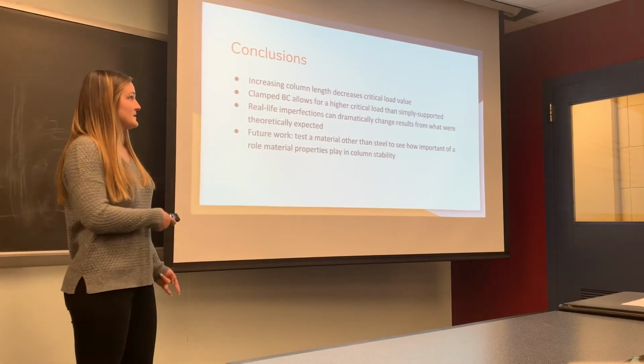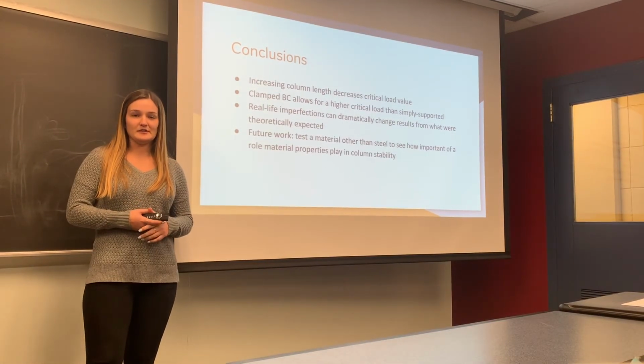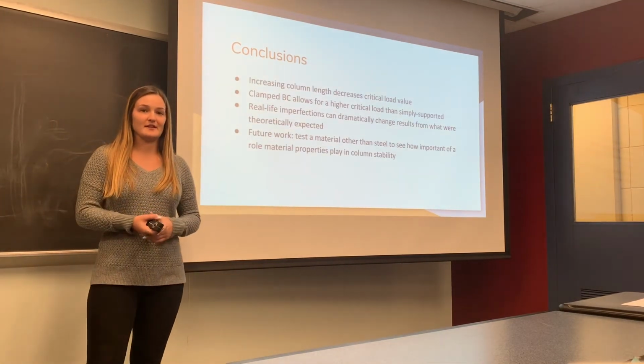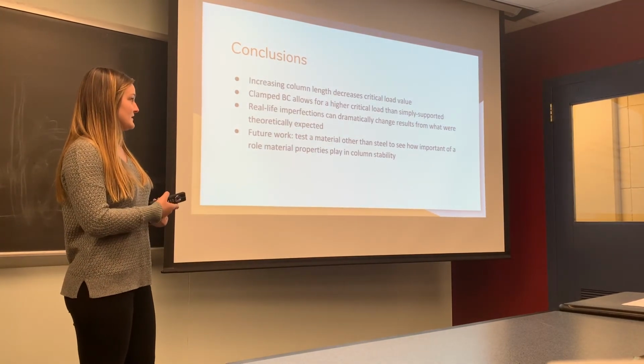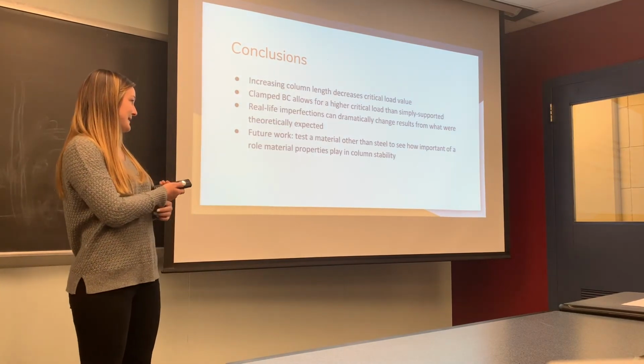Some things we learned from this experiment: increasing the column length may decrease the critical load. The clamped boundary conditions allow for a higher critical load than the simply supported. Real-life imperfections can dramatically change results from what we theoretically expected.